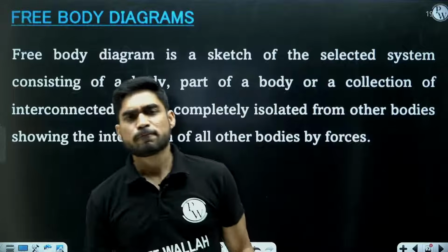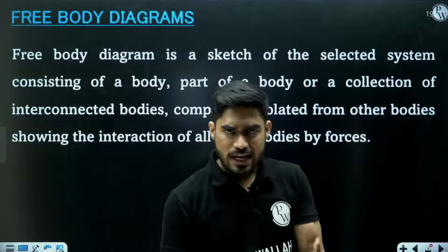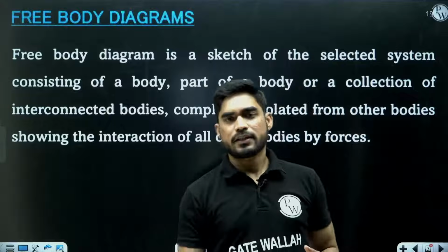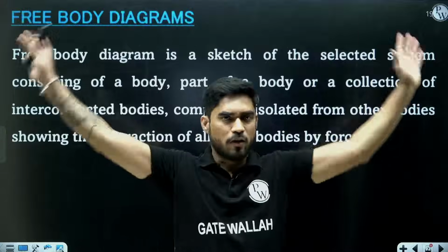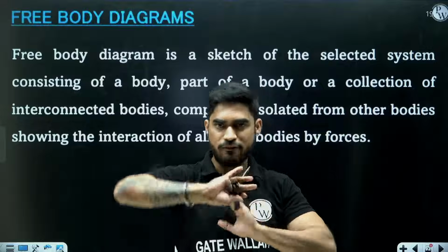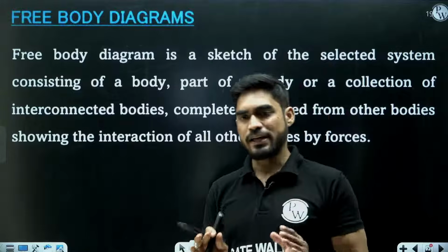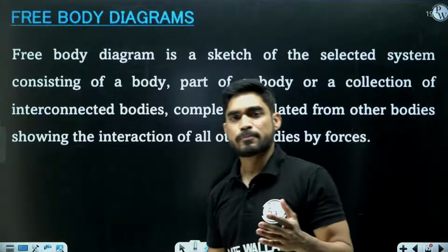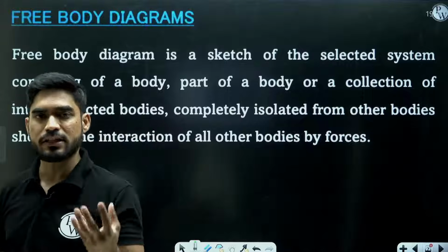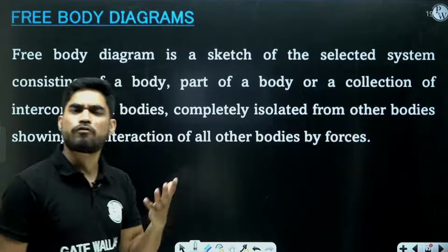So basically, if you want to analyze the forces of a body, then you isolate that body from all the other bodies. Whatever connection they have, you disconnect them, you isolate the body, and when you disconnect the body from other bodies, you need to show the connection between them, the interaction between them through forces.